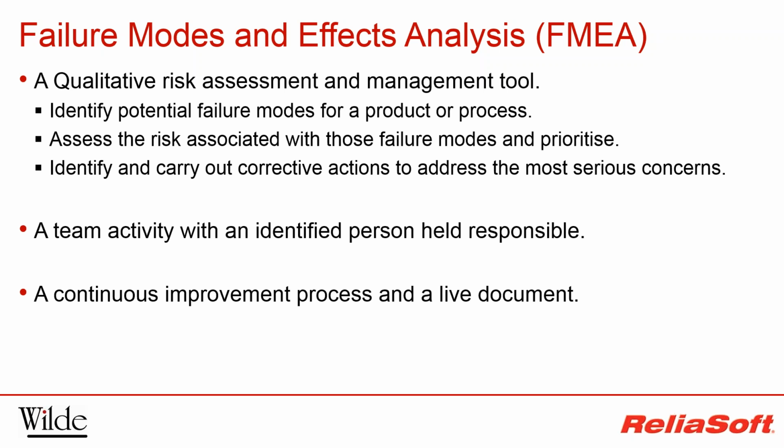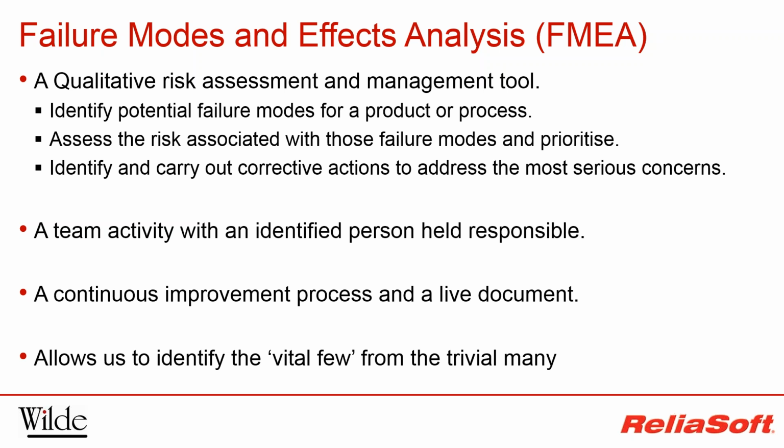The purpose of the FMEA is to improve a product or process through objective and critical assessment, and the document should be used to both encourage and track these improvements. Overall, we want to identify the vital few issues from the trivial many in order to use our resources more wisely. There are many benefits of undertaking an FMEA, as when it's done well, it is a proven tool to reduce lifecycle warranty costs, reduce the number of missed improvements during product development, and it's proven to be effective in the identification and resolution of safety critical issues before a potential catastrophe.